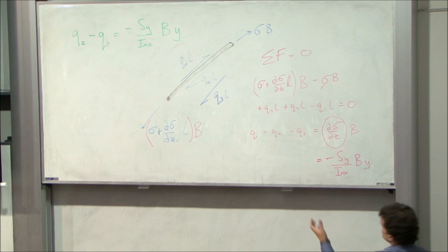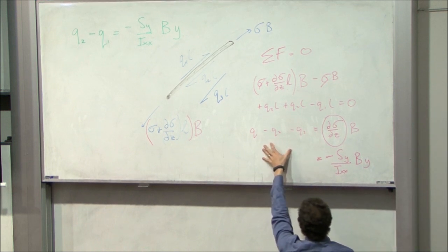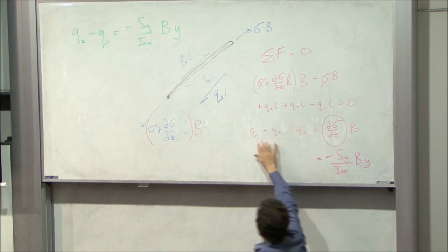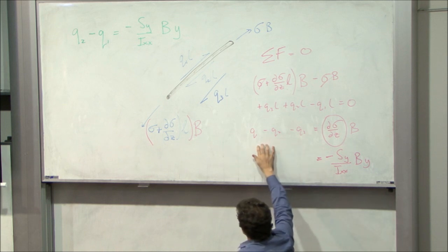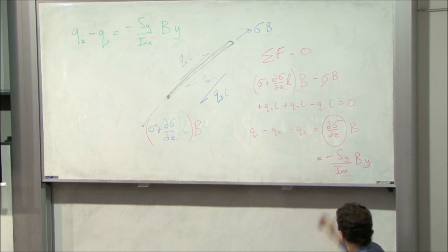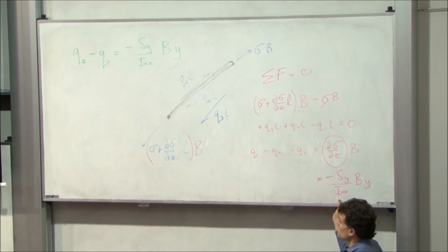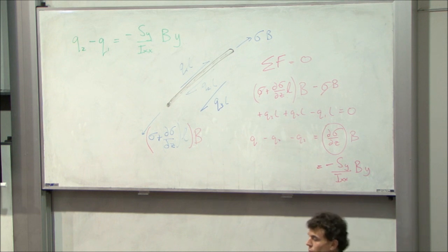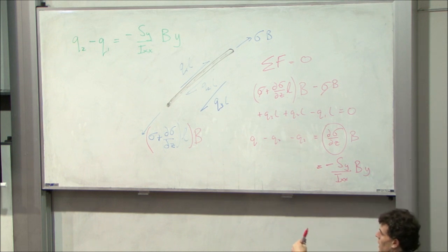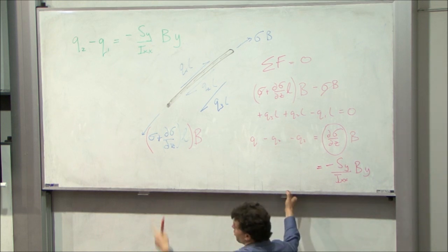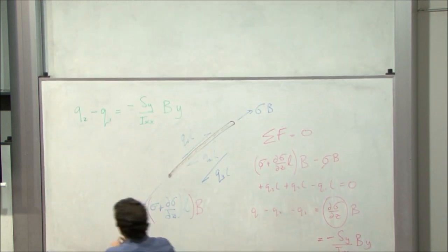So what we're seeing is on the left we've got some shear flows, and on the right we've got this familiar term that's to do with the boom area and the y location for the boom. Now how do we know what the signs of these shear flows should be? Well, the reason we call it shear flow is it's a bit like current flow or water flow. We can think about a direction of travel of the shear. And if we looked at this problem end on,